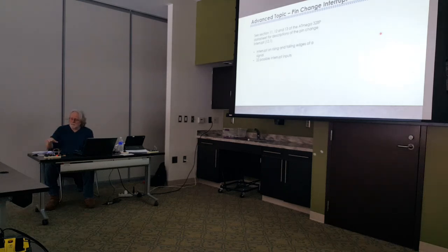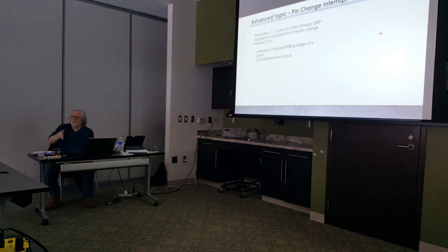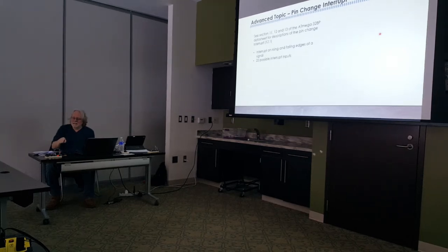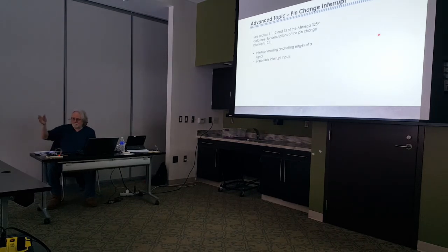When the signal goes low, you interrupt. It can interrupt on a falling edge, or it can interrupt on a rising edge. And we had one called logic level, and I didn't read to see what logic level was, but that's pretty cool. So if I only want to capture signal on the falling edge, I've got that interrupt pin. If I want to capture signal on the rising edge, I've got that interrupt pin. And so the falling edge occurs, it causes an interrupt. You write an interrupt routine that goes off and does something you wanted it to do based on that falling edge.